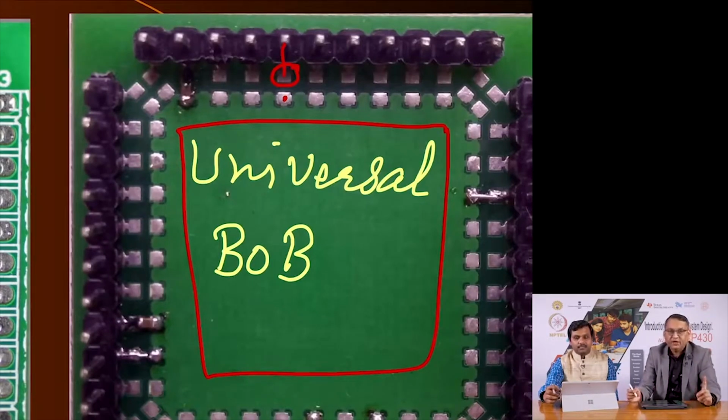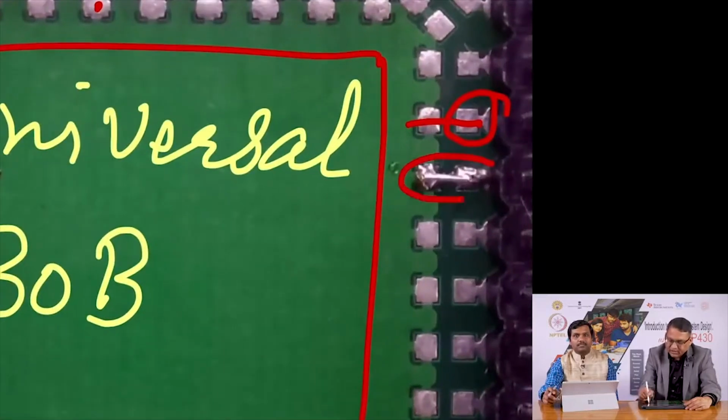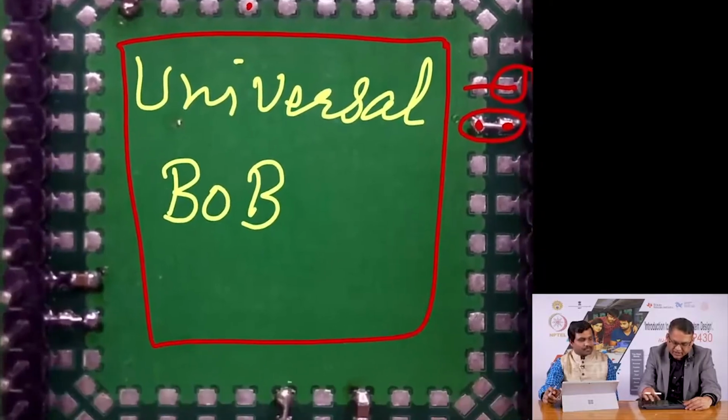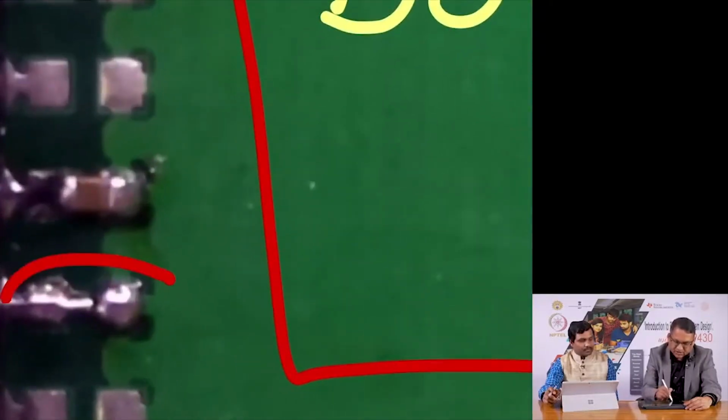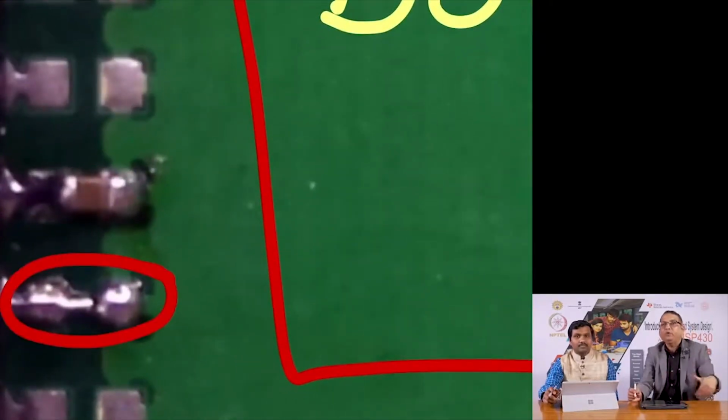Now, if we know that this particular IC has this pin to be grounded, then we will simply short it with a wire, as you see here. You see this wire shorts this pin to the ground plane. Any other wire you see here is shorted together. So, all the ground pins of that IC can be shorted without being committed to a particular type of IC.